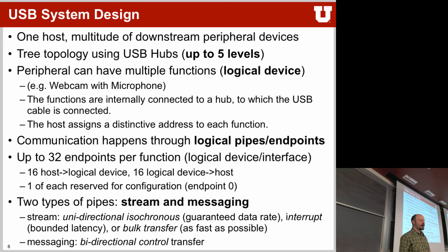That's the first one. Now, sometimes you can have what's called logical devices. For example, this webcam over here has 2 USB functions on there, so it has 2 logical devices inside. Internally, they're connected through a USB hub. So you have to be careful: if you connect too many USB hubs to each other, and then connect one of these devices where you don't think it has a USB hub inside, it could be that it doesn't work anymore because you exceeded the 5 levels.